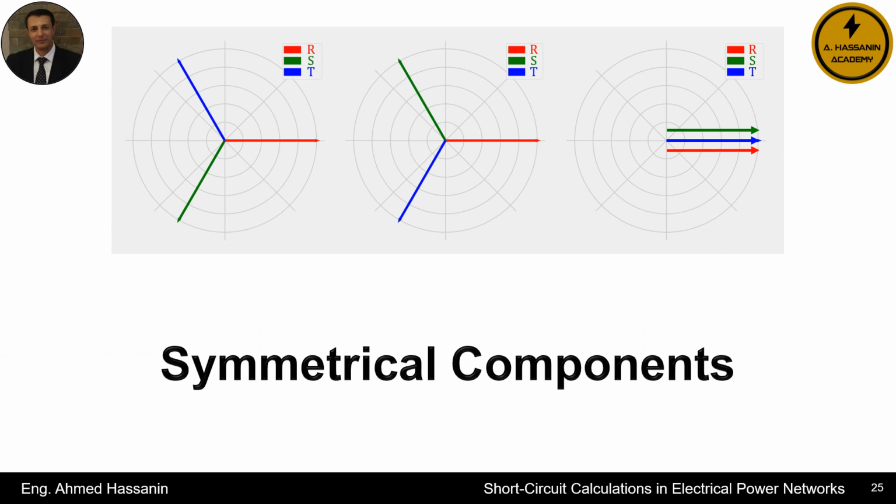In the end, we can say that the symmetrical components method is simply a technique for analyzing and studying faults, not a method for designing protection devices. This means that protection devices will continue to measure the same normal voltages and currents on the three phases. However, based on fault analysis using the symmetrical components method, we will observe that the equations used inside protection devices for asymmetrical faults will differ from those used for symmetrical faults.